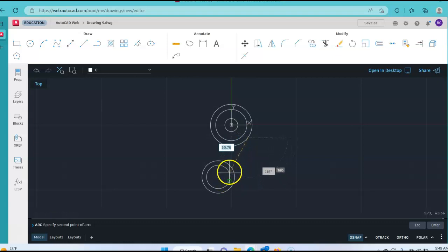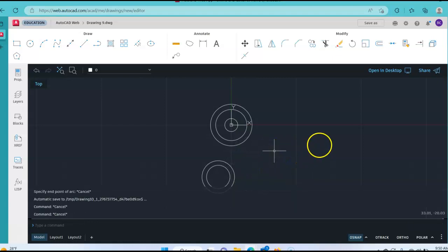Now we've noticed we've got some different tangent points here. So I'll click this tangent here next. Now notice it doesn't really like this, and we get this odd type of shape here because it's not a radius. It's going off of 3 points when we draw that arc. Unfortunately, that's not really a very good tool for us to use in this situation. So I'm going to right click and cancel to get out of that. That's not the tool that I want to use.